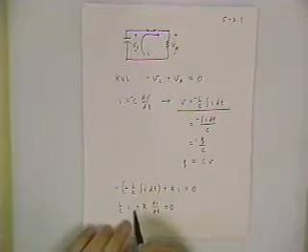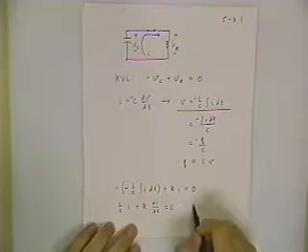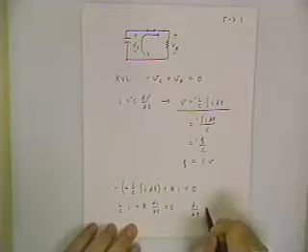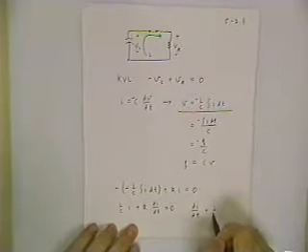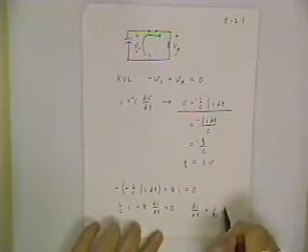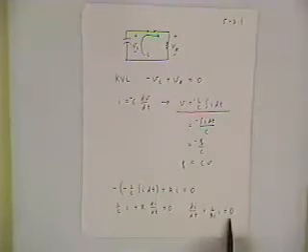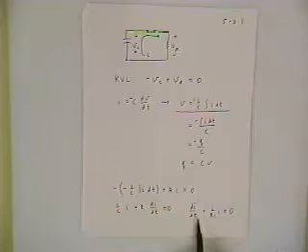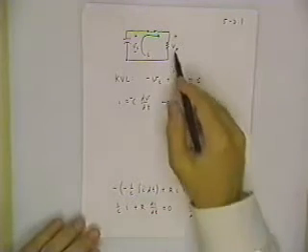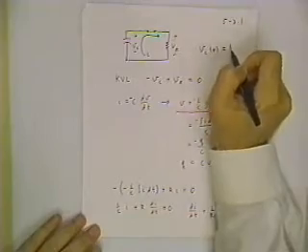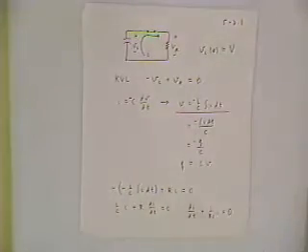And if I simply divide through by R and rearrange terms, I get a standard differential equation, dI/dt plus 1 over RC I equals 0. Now that's the differential equation we want to solve, subject to the initial condition, which we know from having looked originally at the circuit, Vc of 0 is equal to V.